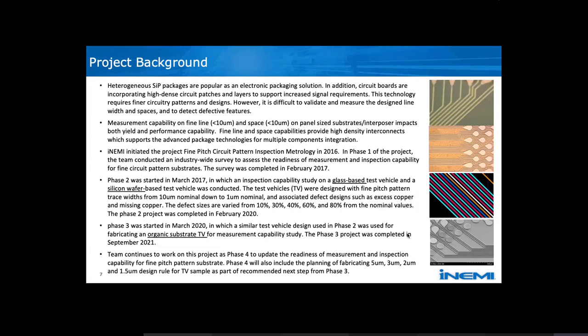Back in the 2015 or 2016 timeframe, IBM proposed this project to iNEMI as an industry study because we saw that fine space of less than 10 micron, especially going to 2 micron and 1 micron, is going to be required for the industry to go into high density circuit patterns and layers, to support all the new requirements like heterogeneous SiP packages. So in phase 1, we started with an industry survey.